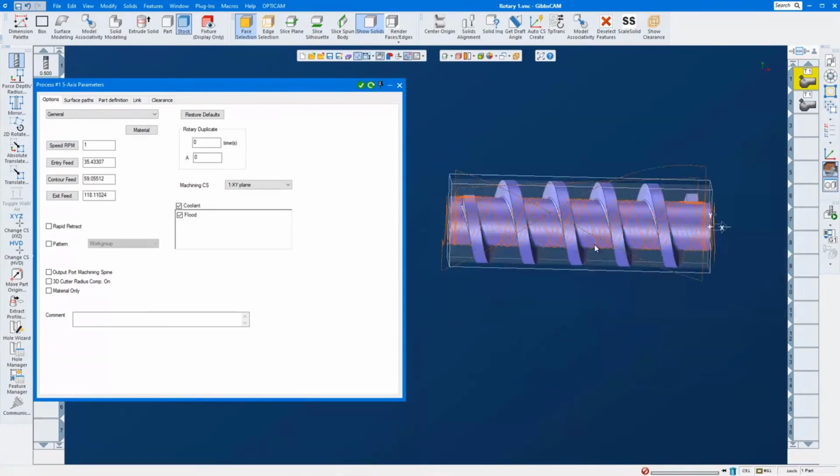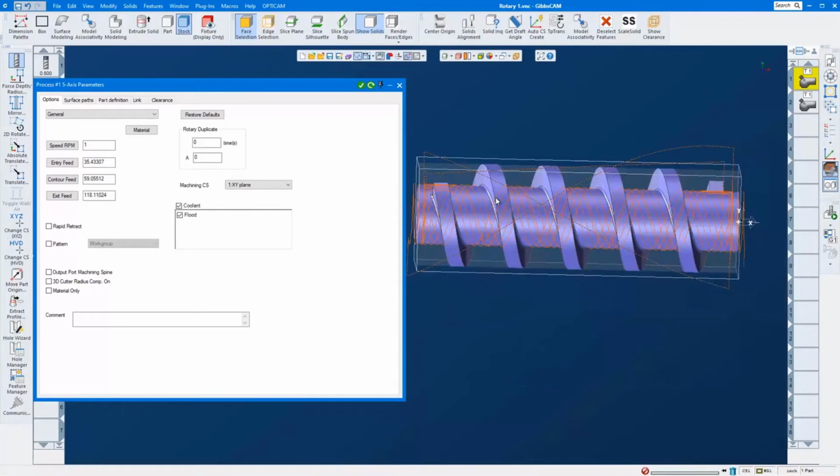This is specifically for parts that are shaped like this, screw type parts. That's all that it will work on. It can be a closed pocket as long as the bottom of the pocket is radial. It can't be flat, because the way this works is that it looks for the smallest diameter on your part, and then works out from that.